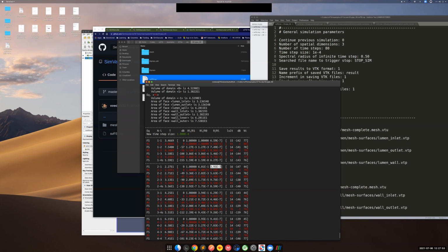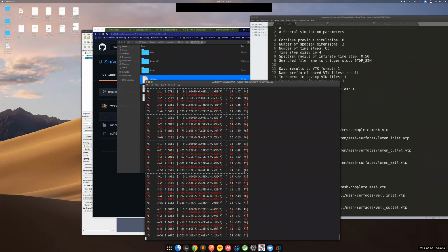The linear solver has converged within the same iteration. So the linear solver's convergence is pretty good. So these are the total number of linear solver iterations. dB is like a decibel reduction. It kind of tries to compute the change in the residue in terms of a log value. And this is the total amount of time that it spends in the linear solver.